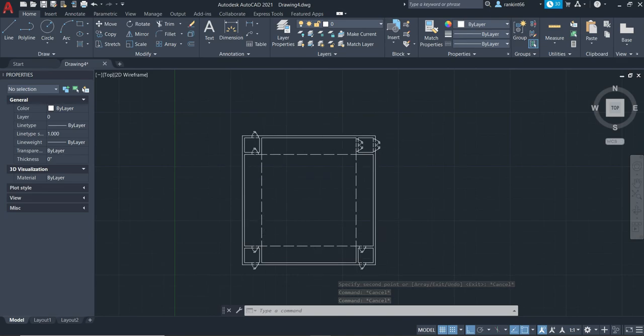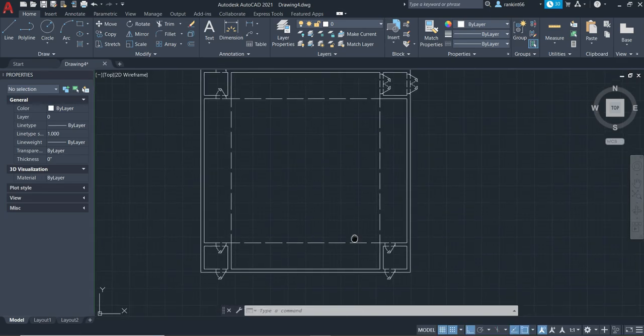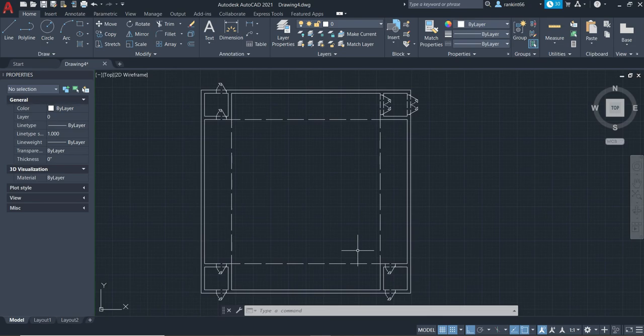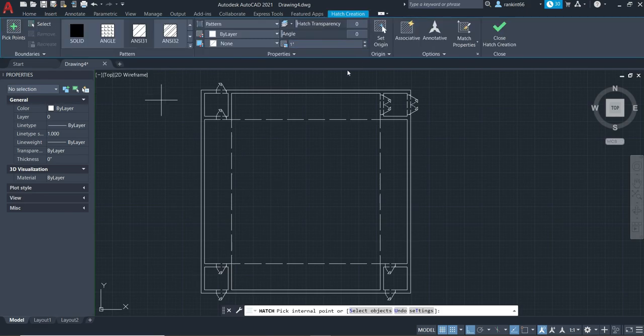The last step for this floor plan or ground plan that we want to follow through is we want to go ahead and give all the hatching to this space. So I'm going to go up to where this hatch tool is, and click on it, and it should open up to this menu. The first thing we're going to hatch is the theater architecture itself. I like to use the concrete texture for this just because it's specific to this, and it's what I commonly always use to indicate that these are the exterior theater walls, and that's all they are.